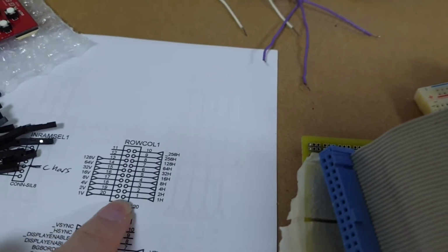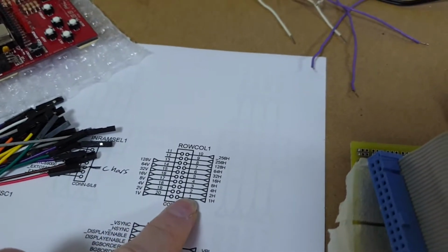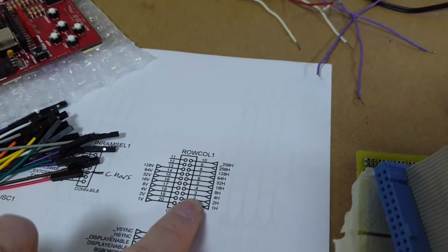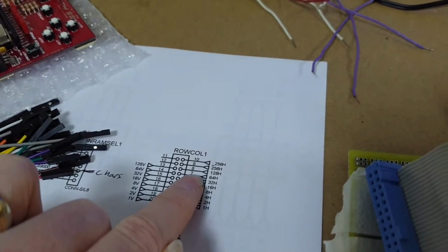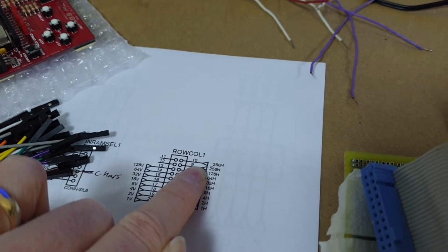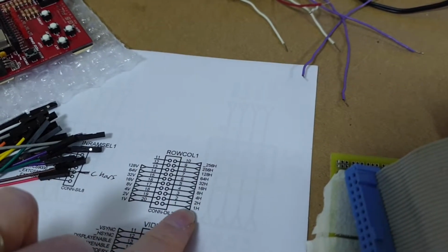When I start pushing it down further, I start seeing more characters. But then when I start engaging the higher video, it switches off the display. So I think what that means is that somewhere up the cable, or somewhere up the header, I was engaging these ones first down at the bottom, and as I was applying more pressure onto the plug, the connection would gradually creep up to here. And I really do think there's something.